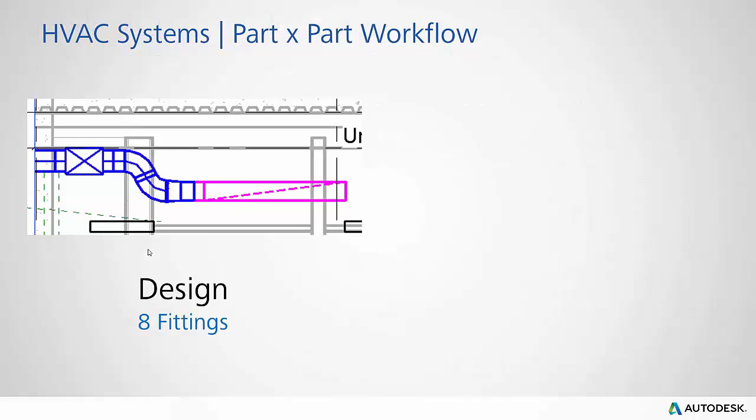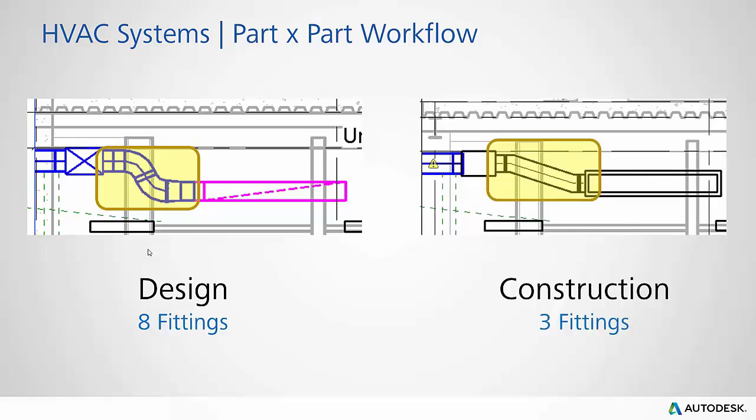This is where you can now work with actual real-world components. So instead of working with a run of ductwork, which might have 8 fittings for a design intent model, you can move into working with construction components, which you can reduce to say 3 fittings.